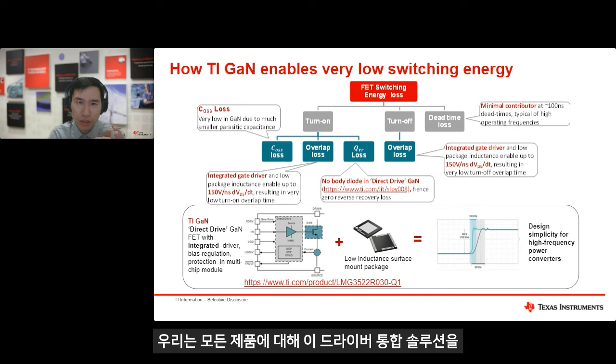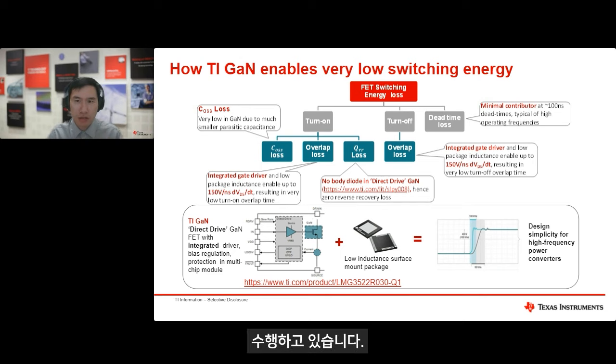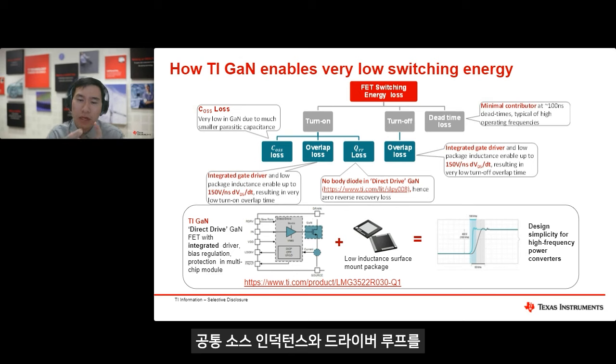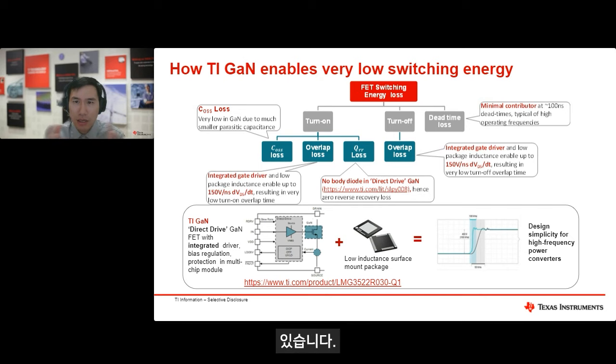We are doing this kind of driver integrated solution for all of our products. With this driver integration, we can minimize all the parasitic inductance of the circuit around the device, including the common source inductance and the driver loop.